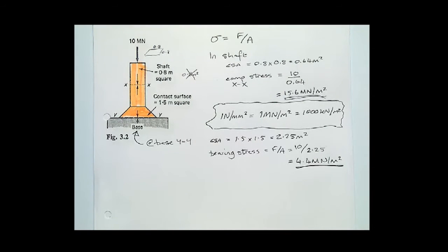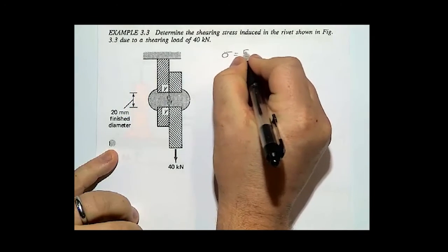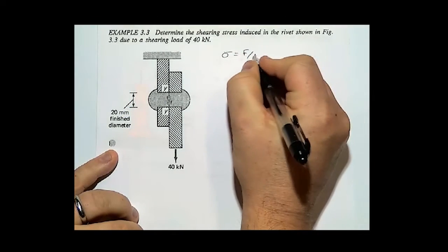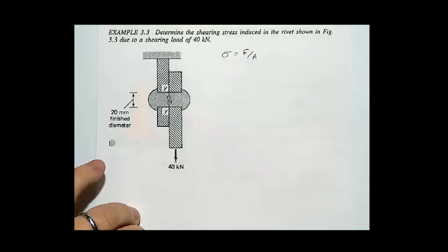And again, whenever you're doing calcs as an engineer, you write them out and then you hand them to somebody else to check them. Most commonly the errors are where people are trying to move between meters and millimeters and kilonewtons and newtons. It's a very common mistake. The force over the area. And when it's talking about the area, you're talking about the cross-sectional area that is coping with the stress.